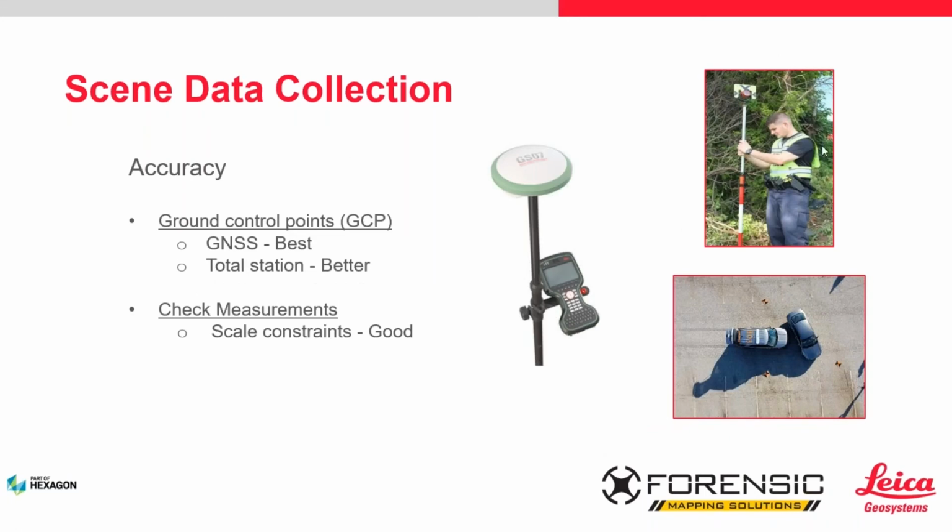The reason why we asked that question about ground control points is ground control points are key to an accurate photogrammetry, aerial photogrammetry project. Ground control points, think of them as anchors. They're anchors in our scene that have known position. And we're going to get into that in a second. And because of the known positions, that allows the software to use those positions, which are going to be three-dimensional in most cases, and process the project in Pix4D to give you an accurate representation of the scene.